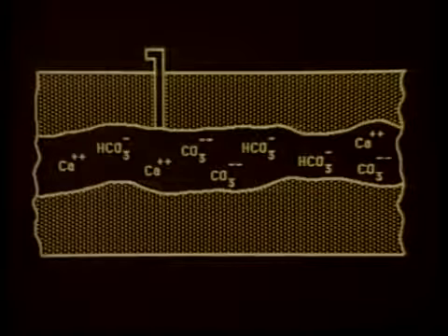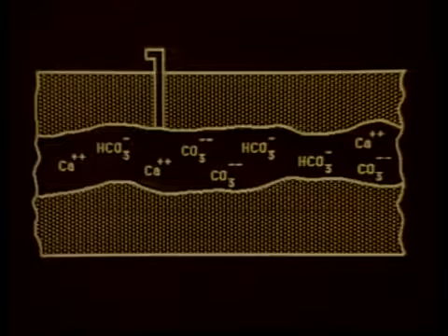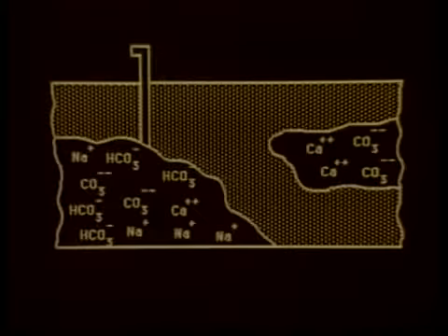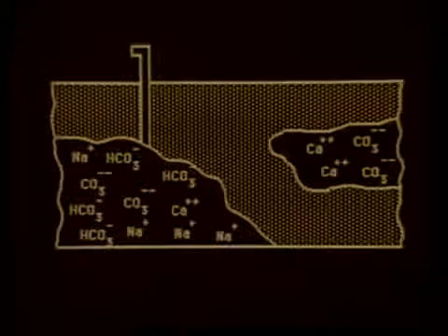Water from a limestone aquifer will contain mainly calcium and carbonate ions. Other ions are present, but exist in relatively smaller quantities. Water derived from this aquifer will have high concentrations of calcium and carbonate ions. Another groundwater source is from a well drilled into a formation of sodium bicarbonate. The predominant ions in this source are sodium and bicarbonate with smaller quantities of carbonate ions. These sources are commonly called soda wells and are usually located at a greater depth than limestone aquifers.